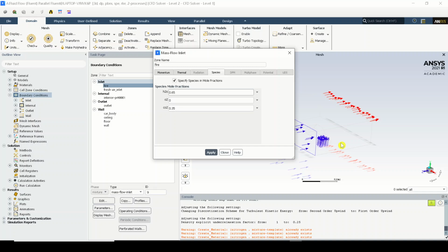Okay, now as per some medical study, the carbon dioxide which is coming out from us, that is from humans, has a mass flow rate of 1e minus 6 kg per second. That is a very small value, but that is the rate of emitting carbon dioxide from a human. I'm not saying it on my own. It was written over there with the proper medical references, right? So in that case also, mass flow inlet must be used rather than entering the velocity, right?